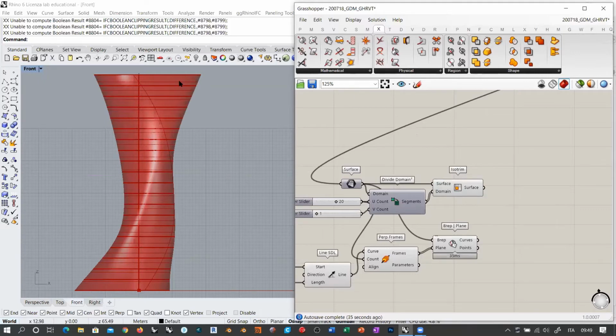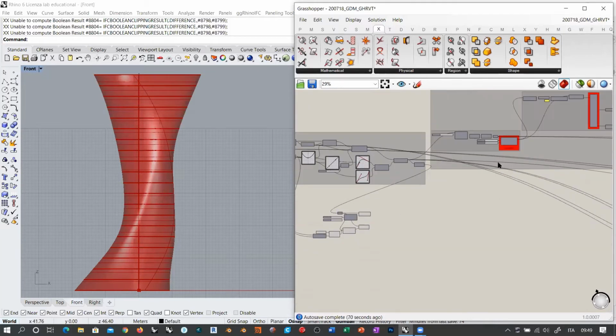and Isotrim. So you see that they are totally not aligned with the actual regular spans that we get from these intersections. So if you want to create a regular facade system, you cannot use the Isotrim, because in this case you are going to produce a totally irregular pattern of panels. So even if they are somehow rectangular, because they are deformed, distorted, non-planar, and so on, but they have this four-side aspect, they are not more simple than the hexagonal pattern that I've created along this surface.